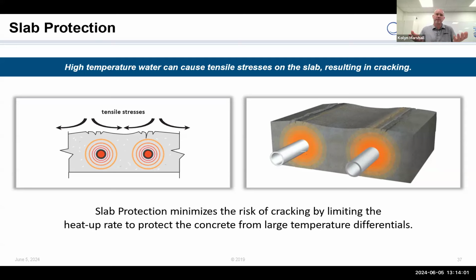They would pour out the concrete and put in the wire and then skim coat the top, or the wire floated up. It was almost always near the surface of the concrete. So you had very little mass above the wire, very little diffusion area to diffuse the heat that was being produced. And when the switch was flipped, that wire was instantly hot everywhere, and there was no way the concrete could absorb that much energy and adjust itself. So therefore it cracked. It was deemed that shock happened above 150 degrees electrically. That rule has become the standard in the industry today.